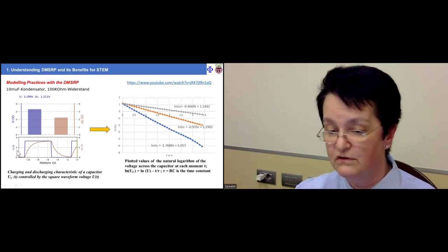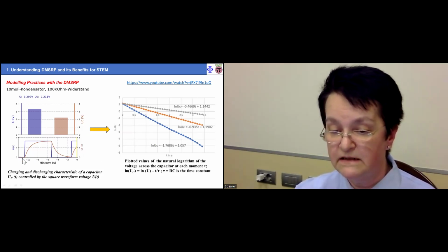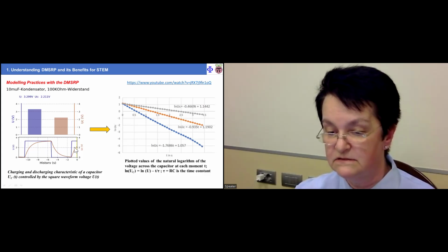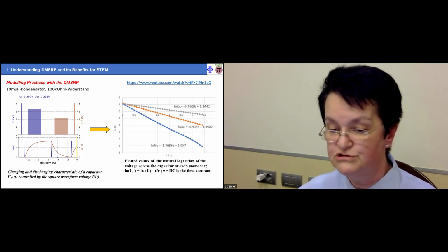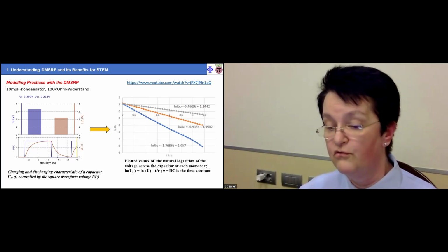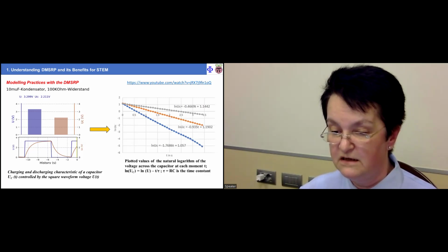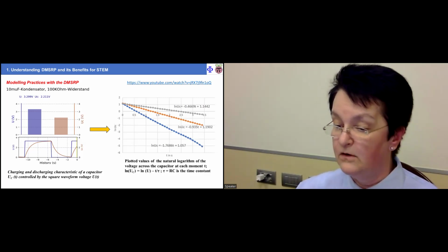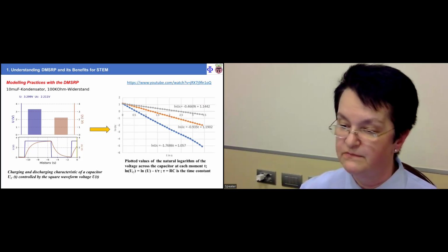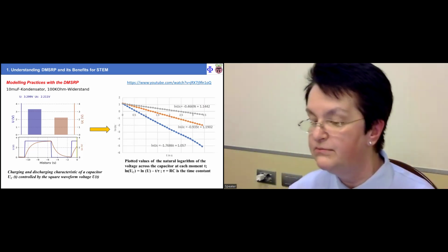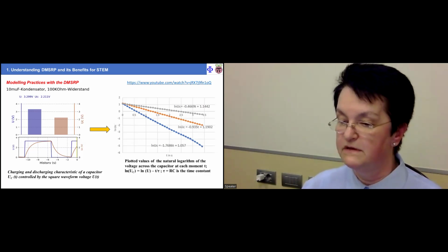The voltage across the capacitor is shown in brown, and a step voltage is created at the pins of the Raspberry Pi as a wave voltage. So the growth and the decay process can be modeled with exponential functions. Also, the data are recorded and stored in a CSV file, which can be processed with LibreOffice, running directly on the Raspberry Pi.